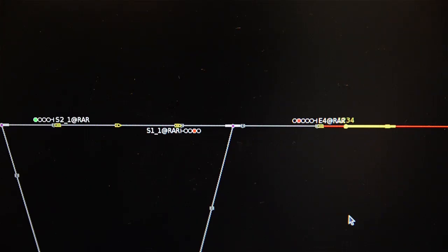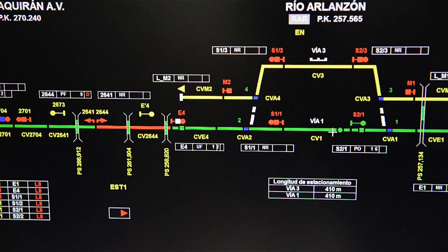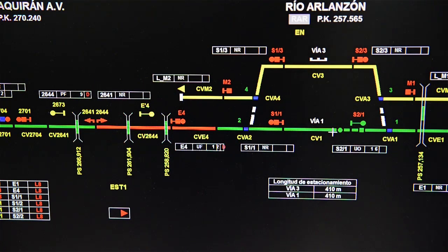The on-sight acknowledgement appears on the screen, and after recognizing it, the train enters in on-sight mode. We can see now in the screen of the traffic simulator how the train is passing the on-sight signal. And after that, the signal switches to red aspect. And the train starts running in on-sight mode inside the station. Now in this image, we see in the local traffic control desk how the train is passing the signal E4. Now the train has passed the signal.